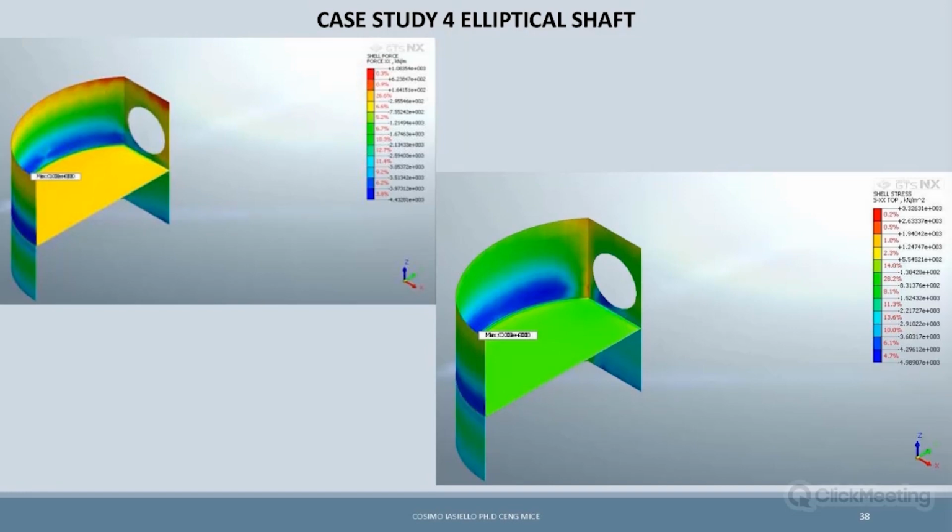Because as you know, in MIDAS for each shell force we have three values: the top, which is the outer in this case, the bottom or the minimum, which is the inner side of the excavation, and then you have the average. Depending on our calculation, we could choose one of them. Okay.